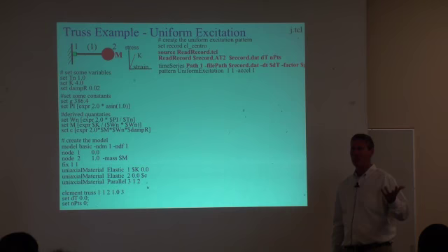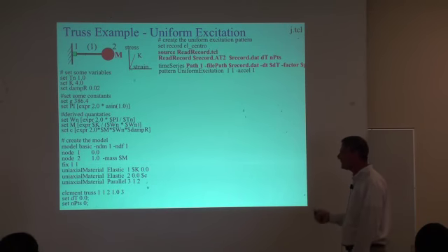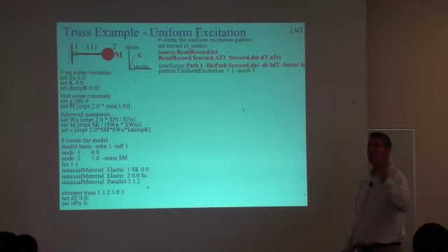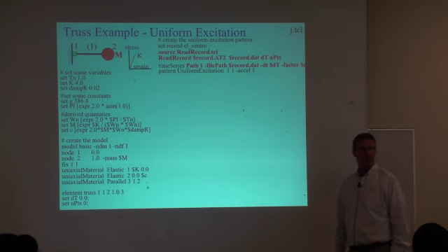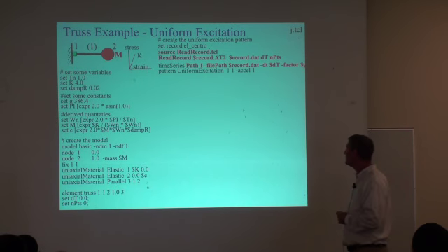Then it'll do some little cheesy integration, because uniform excitation needs the acceleration, so it does some cheesy integration from the displacement to give you the acceleration. So I strongly suggest never using the other options that are there, even though they are there, and always specifying the correct acceleration you want yourself. Don't rely on me to give you the best option. Figure it out yourself.